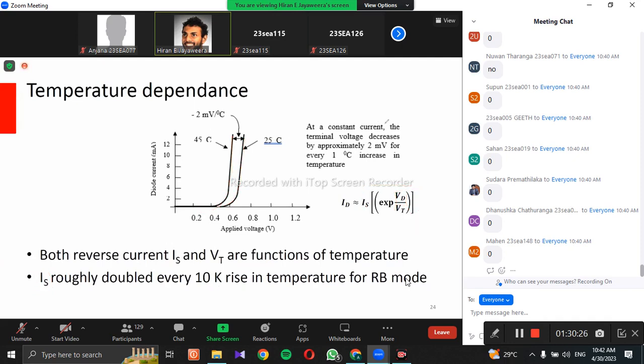You don't need to worry too much about this, but remember there is a temperature dependence. This is also a temperature-dependent parameter, although it's called a constant, it's not really a constant. So there is a complex effect. It's out of our course scope, but remember the temperature variation effect on the system. That is the main thing that you need to understand. And you should be able to explain that also by considering electron-hole pair generation and so on.